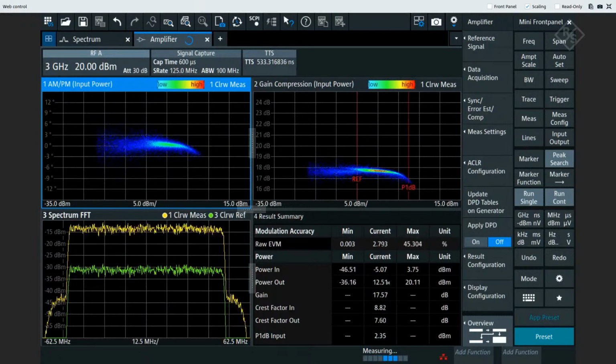is the same. However, what is different and probably relevant for your evaluation of the device under test is that the signal going into the device no longer has a crest factor of 10 dB but only 8.8 dB, because our driver amplifier in this case also operates in its nonlinear region and also compresses the signal. So the actual compression inside my device under test is only a little over 1 dB. And thus also the huge difference between EVMs in single channel mode and dual channel mode.